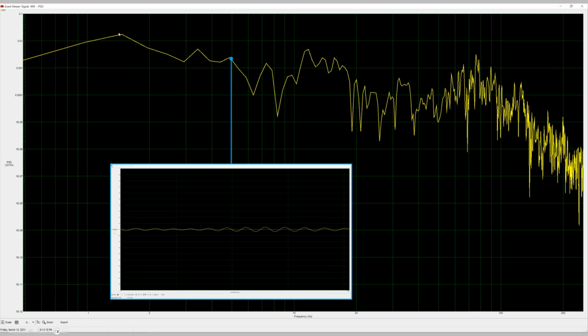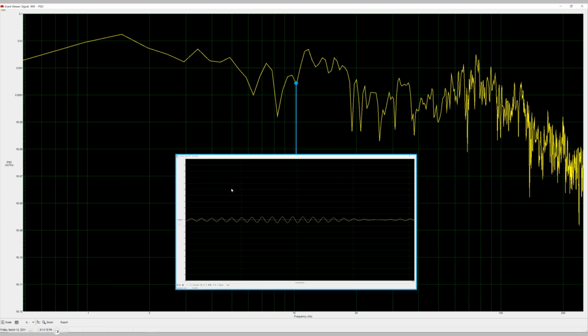And then I say, okay, what does it look like at 5 hertz? I can pull that out. I can do some averaging on that overall amplitude across that window, and I plot that. And then what does the 10 hertz look like? And I do the same thing, do some averaging, plot that. And of course, those are 3 little examples, but imagine across this whole PSD curve, there's potentially hundreds of those analyses that are taking place.